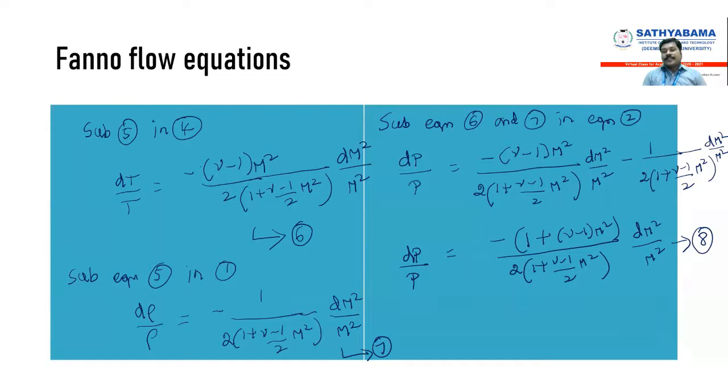So it changes with respect to Mach number only, since it is very easy to solve. With respect to friction, the Mach number is getting varied, so we are going to solve all the flow parameters in terms of temperature, density and pressure. And then we have to estimate the total pressure. So what is your total pressure, your P naught? You are going to use this relation.